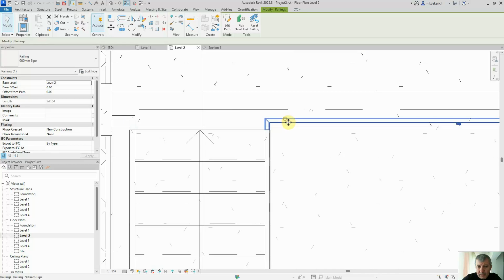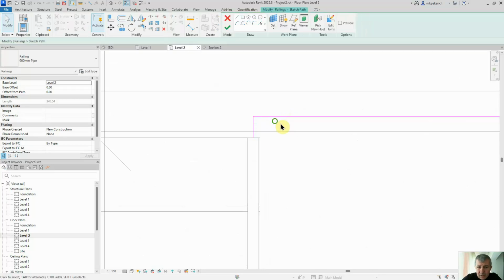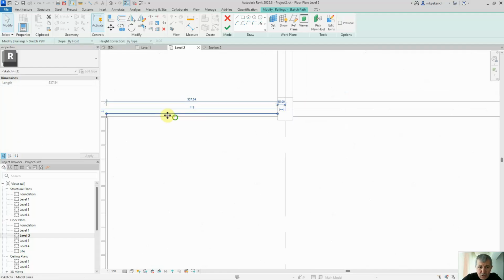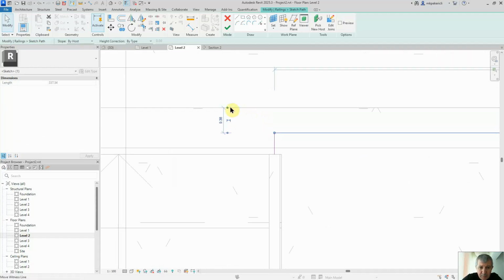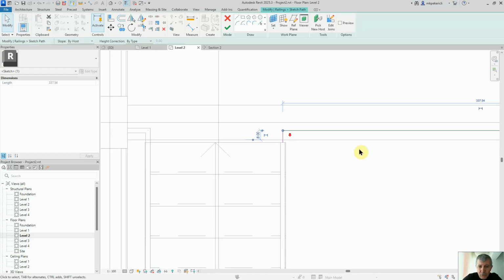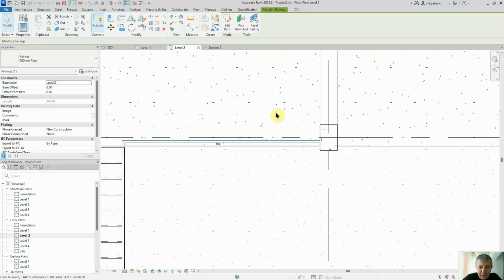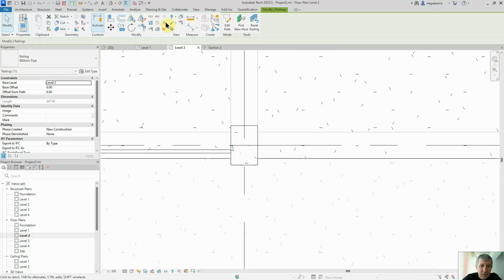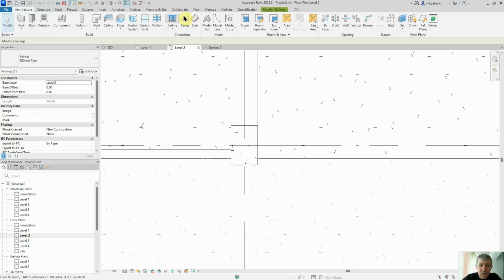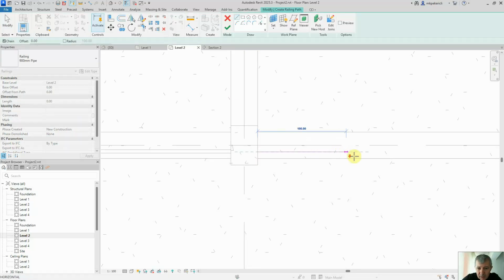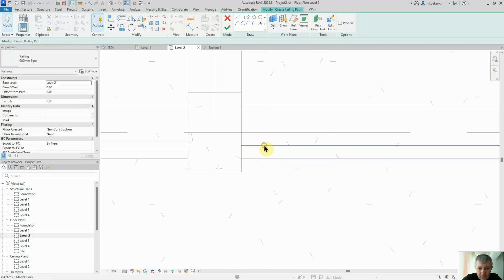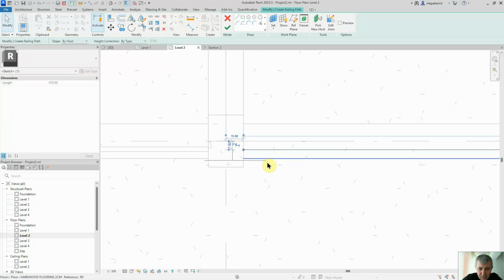Alright, so we will pick this one, edit. So we will measure again its distance, this edge. Yep, I will pick this. It should be 8. Enter. Okay, perfect. So finish that one. Okay, now the next railing should be architecture, railing, somewhere here, up until there. But I would like to test if this is also 8.